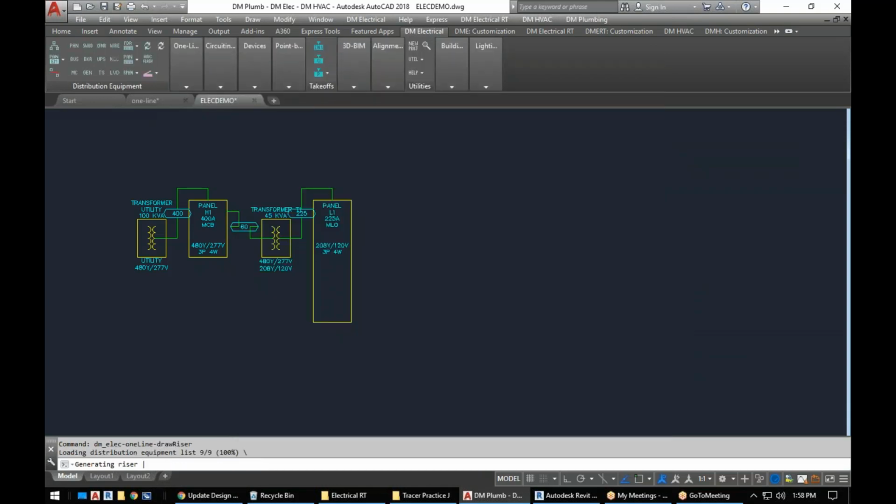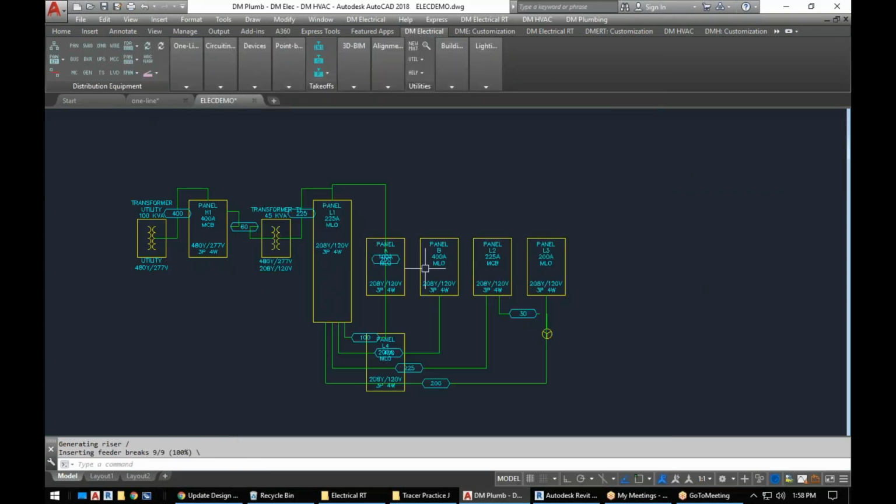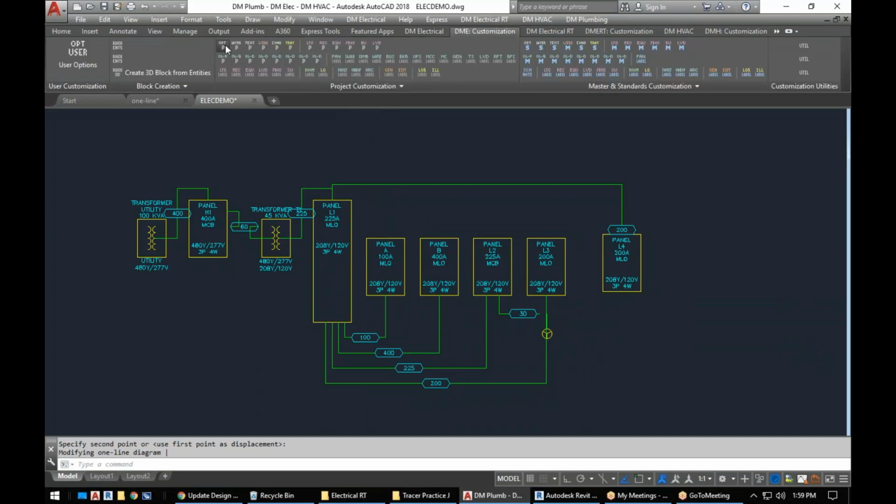So if we change that from side to top and bottom, actually, no, it depends on where the connection is. If you're connecting to the bottom of a feeder, you connect out the bottom of the other feeder. If you're connecting to the top, you come out the top of the original panel. So it does the adjustment there. Again, that's just a question of how you like to draft your feeders and where you want them coming out of the other panel. And if it did something like this, you would go and make that adjustment and pull that over there, so it's not as messy looking.